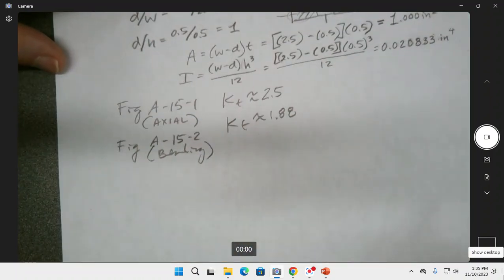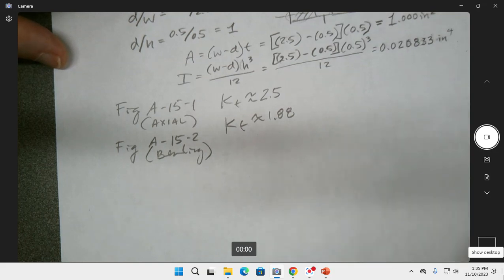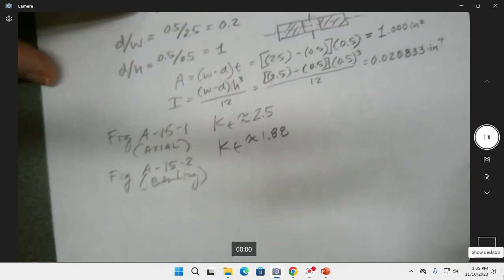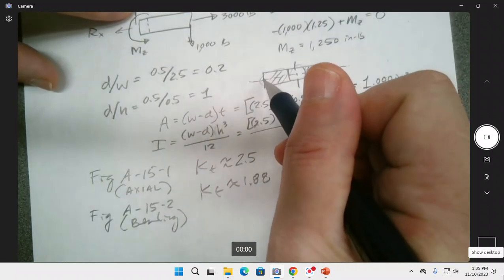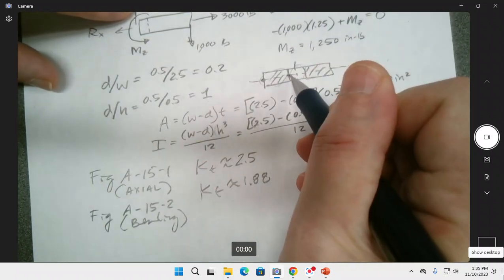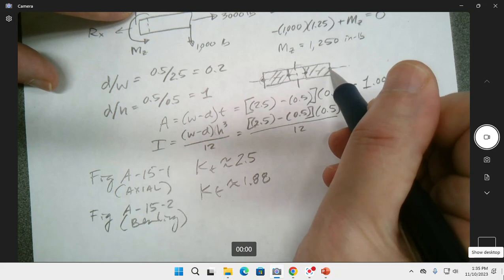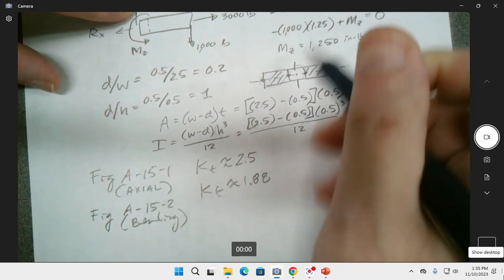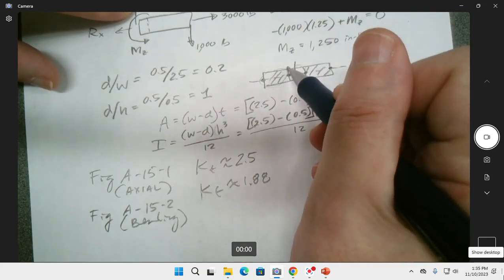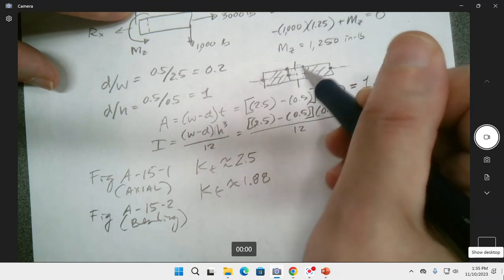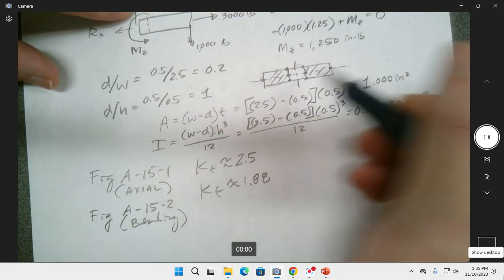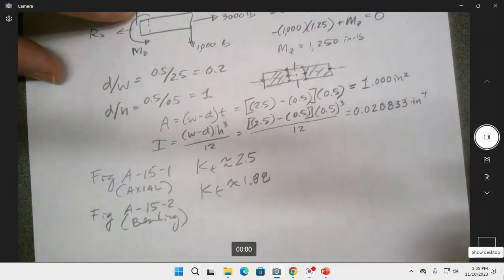There's no torsion. There is direct shear. I mean, there is a chance here, but it's never the same place as the bending. Let me see that. It's transverse shear, not torsional shear. Its maximum is located right here, but the bending is probably going to be right here at the top, and then compression at the bottom.